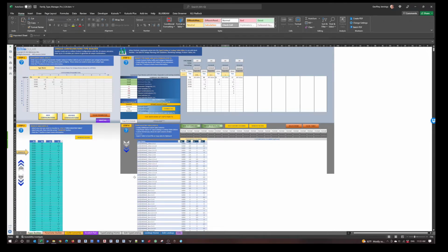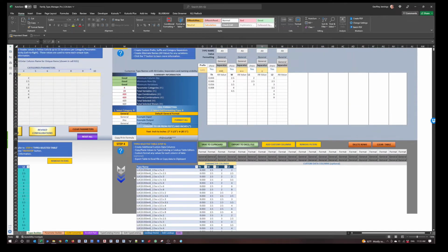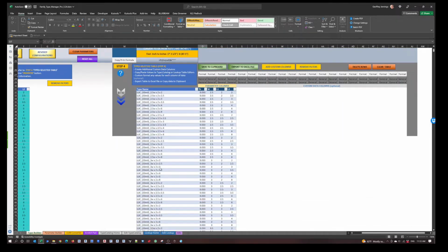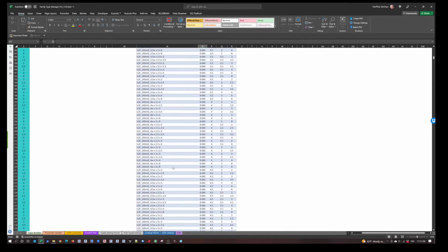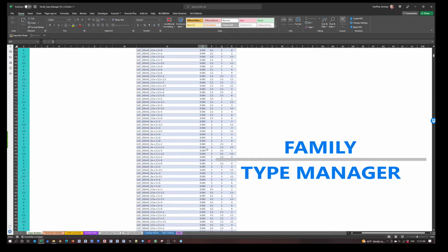And at this point here, I don't like this value being shown as 30.003, so I'm going to do a modification. I'm just going to call this now 43, 56, and 68. So now I'm much happier. I've got this thing laid out the way I need. I also prefer to have a little bit of a space for our leg utility clip, or L utility clip, make a little space. So we have now automatically named all 420 different family types in a matter of seconds.